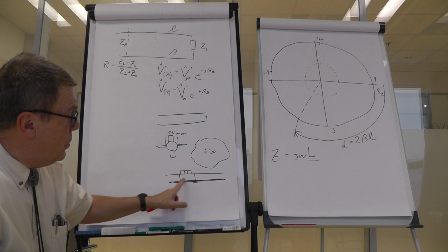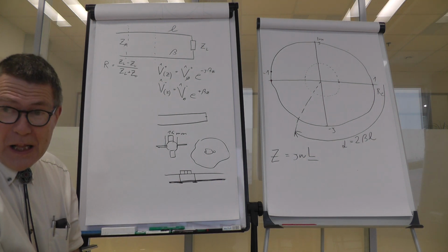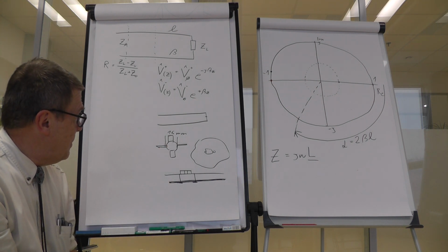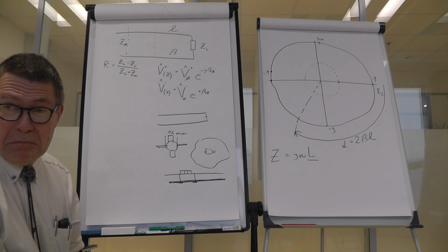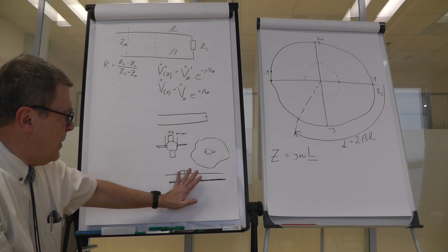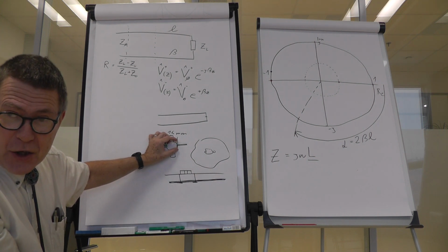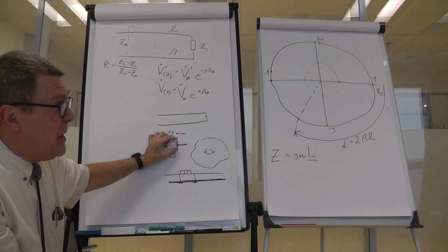You have 2 in parallel, so the resulting inductance is just 1/2. But that forms a good oscillator at, say, 26 gigahertz. So even small inductances resulting from small connections between circuit elements might be a problem.